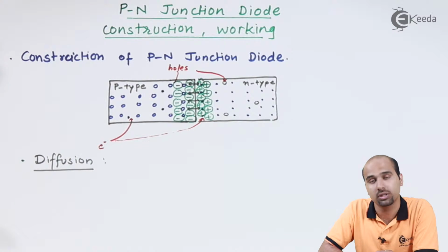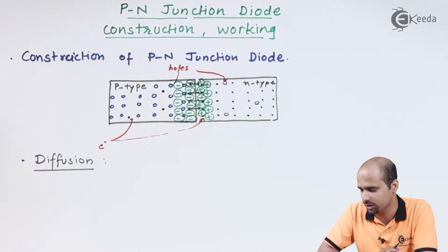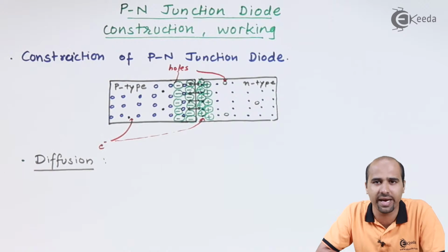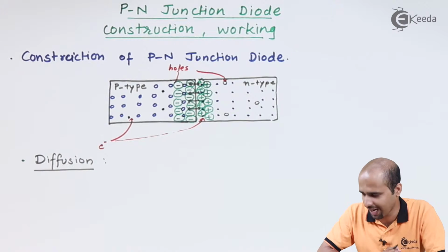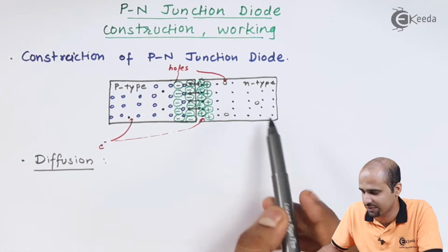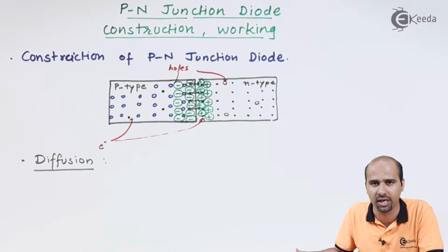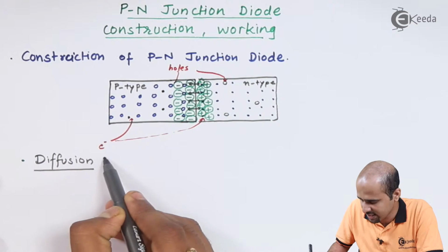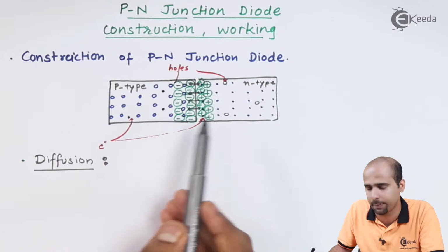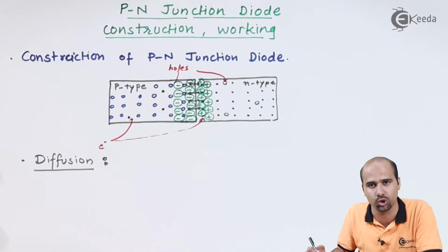Mind well, the beauty of that diffusion is I just recombine the holes and electrons without applying any external potential. I haven't applied any external wiring circuit over there to push them from one region to another region. No, it is not necessary, right? So that's why it is called diffusion. They themselves form the movement from n-type to p-type and p-type to n-type. So this is called diffusion.